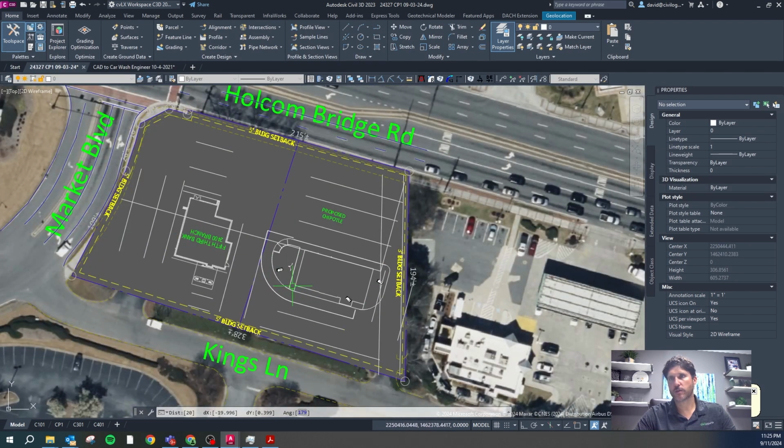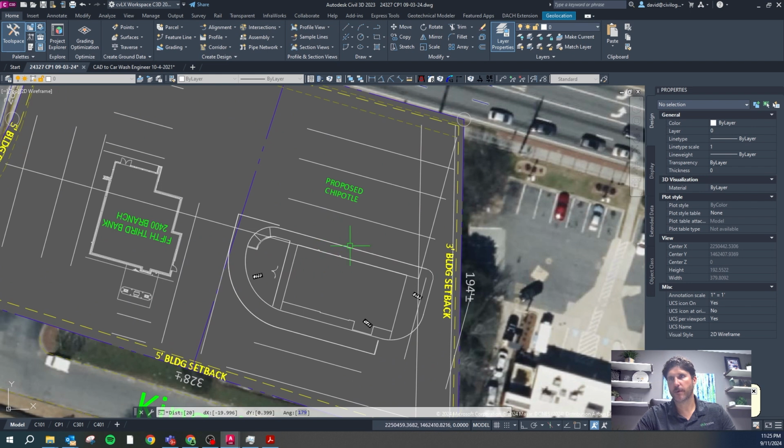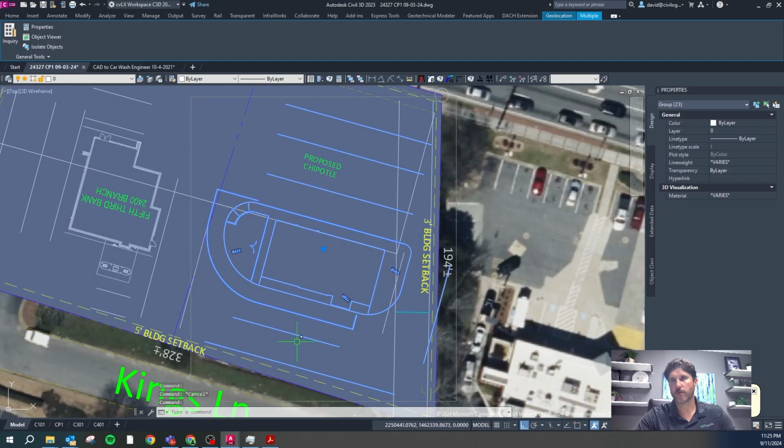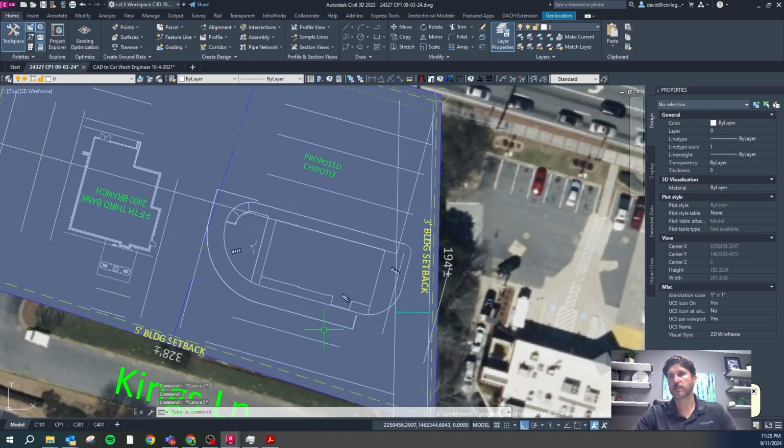And then I took the Chipotle and I just wireframed off the sidewalk 18 feet, 24 feet, and 18 feet, and just offset it. And then off this drive through in the rear, I just offset another 12 feet so that cars can get past. So this really could be my curb line here. We don't necessarily need this last line.